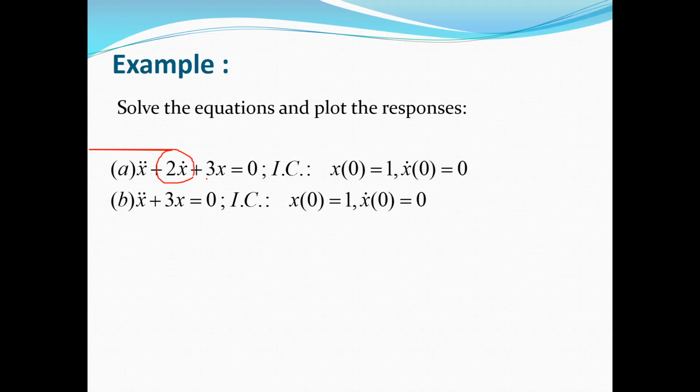You will see later when we extract the governing equations for a system with damping, we have another extra term in our equation of motion, which includes the first derivative of x with respect to time, and it's called the damping term. Here you can see the initial conditions, because this is an equation in terms of time. We have initial conditions, so here we call them initial conditions, not boundary conditions.